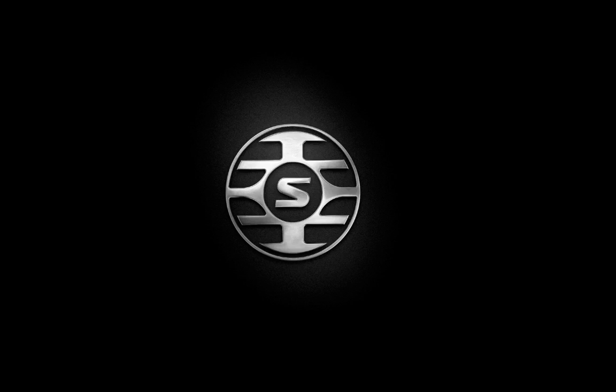Okay. What is the sensitivity of the KSM8 as compared to the SM58 and the Beta 58? And is it already using neodymium magnets, or will we see a beta version in the future? That's a good question. Sensitivity is 51.5, which is a half a dB shy of a Beta 58. And it's about 5 dB hotter than an SM58. So it is a neodymium magnet. It does have a new pole piece to kind of harness as much of that magnetic energy as we can.